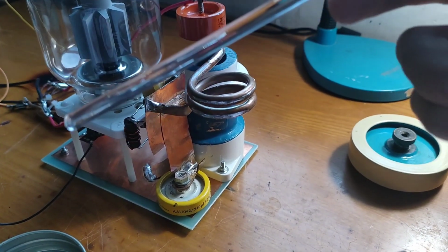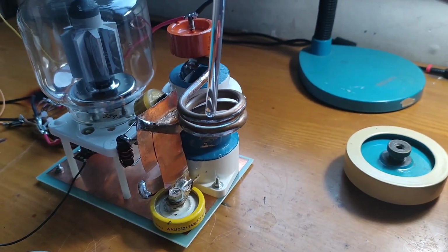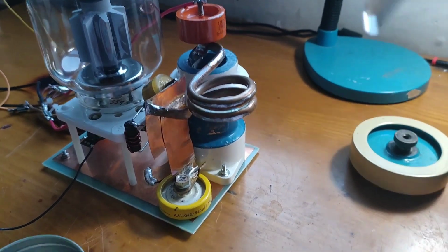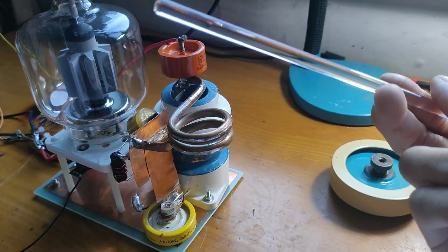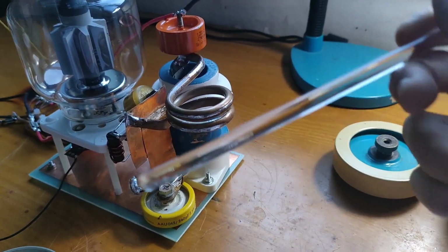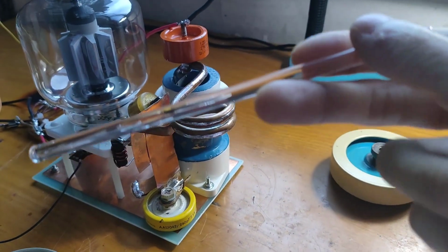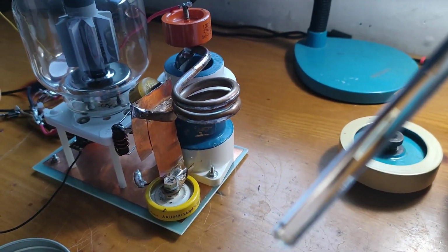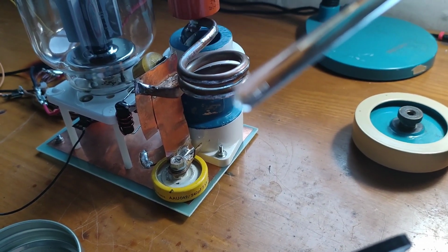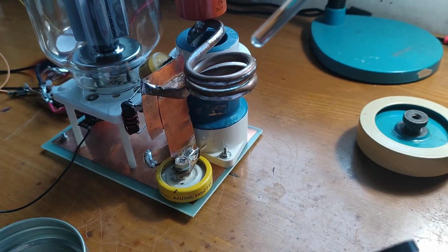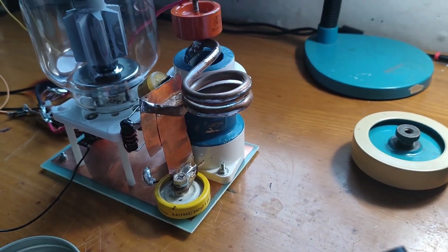So in that situation, you can also try to increase the voltage to see if that happens again. Or if you see the stop of the oscillation start at a higher voltage, at a higher load, after you have increased the anode voltage, that means your feedback ratio might be reasonable, and you can increase the voltage to the anode while gradually tuning it.